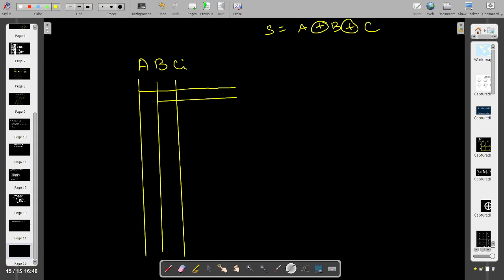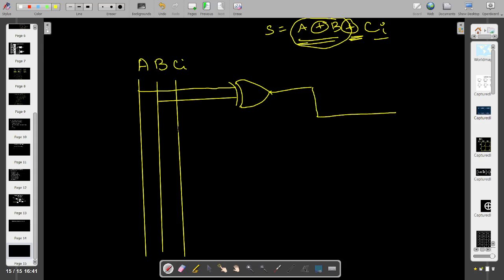This is actually you can do with all these things, but we go for this kind of representation. First you will exclusive OR these 2 alone. After that, this resultant A exclusive OR with B is exclusive OR with CI. So we got this result, which would be exclusive OR with the CI. So what do you get now? We get this sum output.